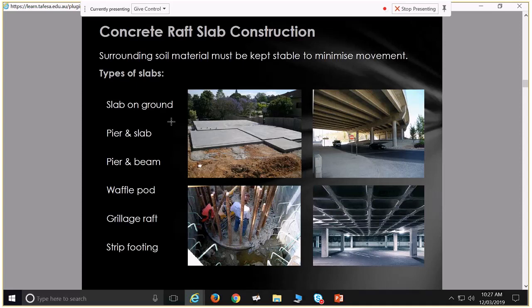So you have all these squares set out. That's because we don't need to have concrete everywhere. We can increase the strength of something by increasing its depth. Hence, where we have these beams, we make them deep. So if we increase the depth of something, we increase its strength. But if we make this whole slab like that, 400 millimeters deep, that's a lot of concrete in there. So to achieve that depth, but not use all of that concrete, you just put out spaces to say we don't want concrete in this bit, this bit, this bit, and you set up a grid. So you still have the depth of profile, but without the same volume of materials used for that. So exactly the same principle.